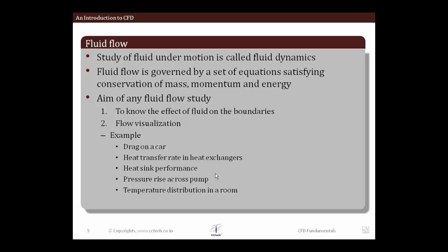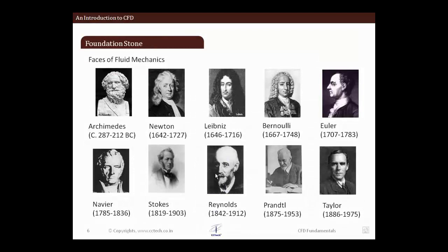So these are the twofold purposes of fluid flow study, which is to find out the effect on the boundaries, which can be flow boundaries or wall boundaries, and we are also interested in doing some flow visualization. Now we're going to look later on at the advantages that CFD offers, because it's an introduction to CFD, as you can see. But we will see that this flow visualization is a very important aspect where CFD scores over many other phenomena that we usually have.